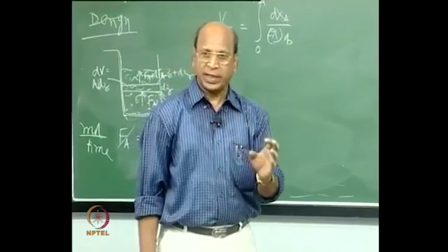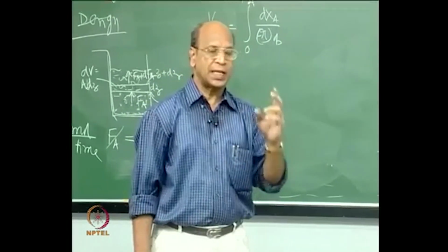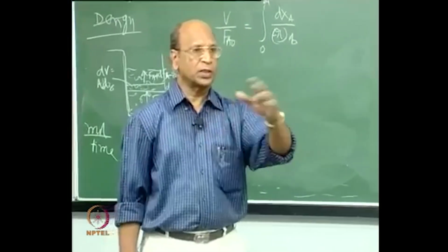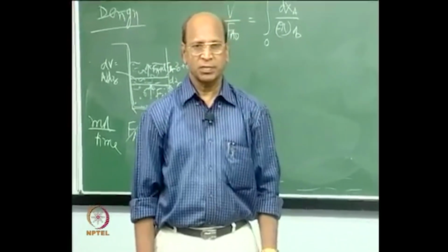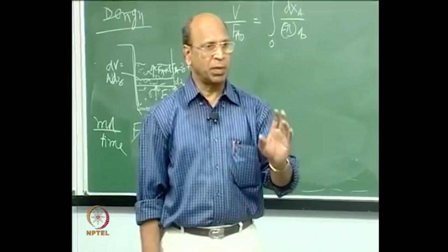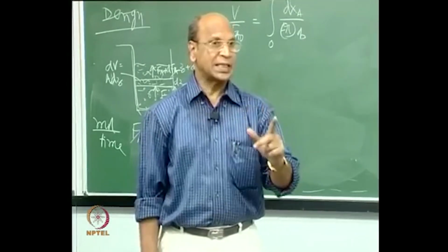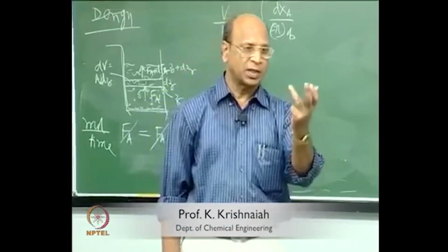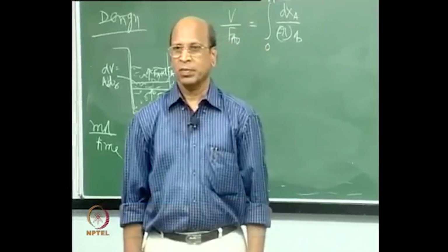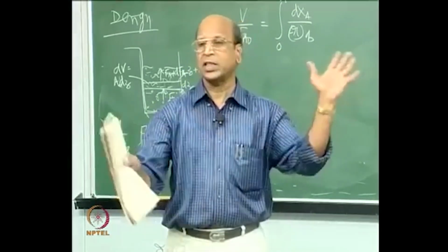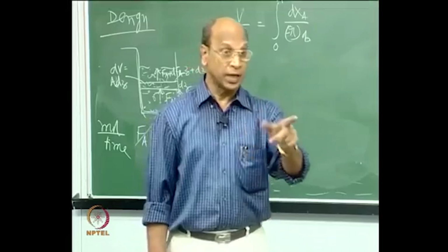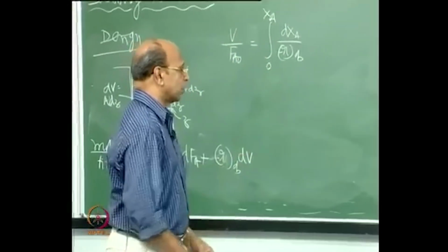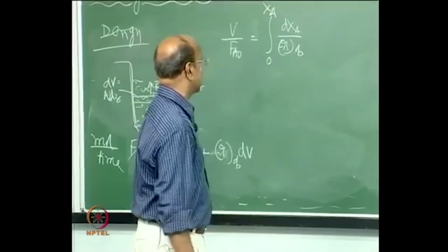But what you have to remember is that the mass transfer coefficients and heat transfer coefficients will change the moment the way the phases move changes. The movement of phases will determine mass transfer and heat transfer coefficients. That is why for each and every equipment you have different mass transfer coefficients and heat transfer coefficients, whereas reaction rate is the same for any system. Reaction rate will not change. That is why heterogeneous systems are very beautifully exciting things.